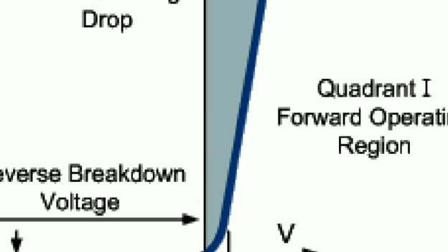You show voltage on the x-axis and current on the y-axis. At the start there is no current flow, or very little, but from the knee voltage, 0.3 or 0.7 volt for silicon, there is a sudden increment in current, and that voltage we call the knee voltage or cut-in voltage. So these are the forward characteristics of a diode.